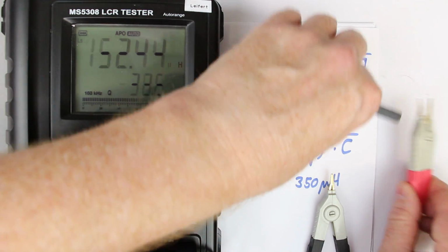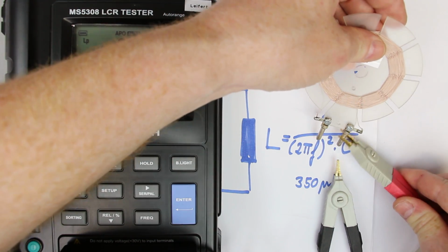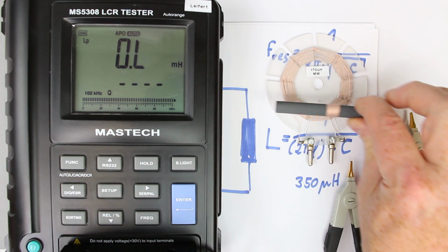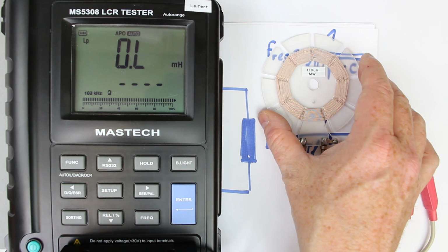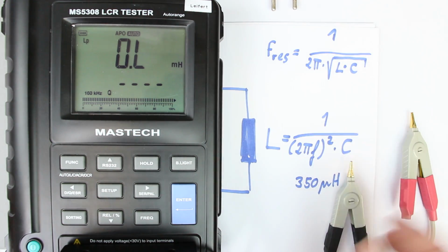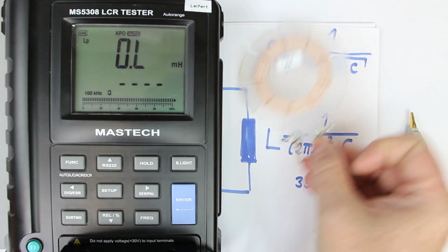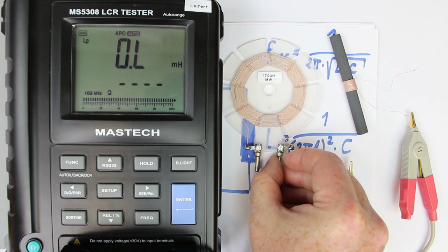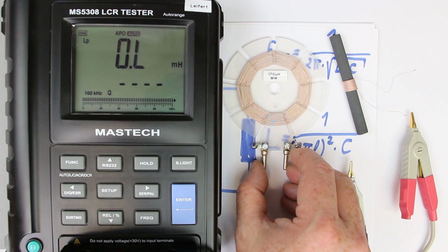Well, let's compare it to the one I have wound by myself, and we don't have to check it. It's already written that it's nearly the same as the ferrite-rod antenna. It's only 170 microhenries. You say there's something wrong. Now the reason is simply that these antennas are intended not for a 290 picofarad capacitor, but for a 600 picofarad capacitor.